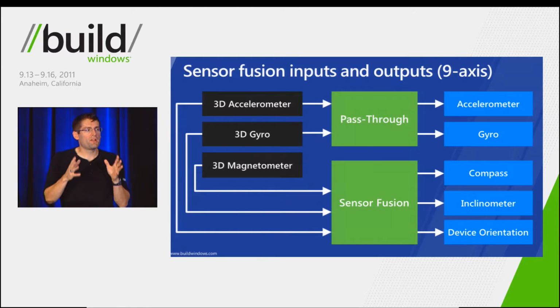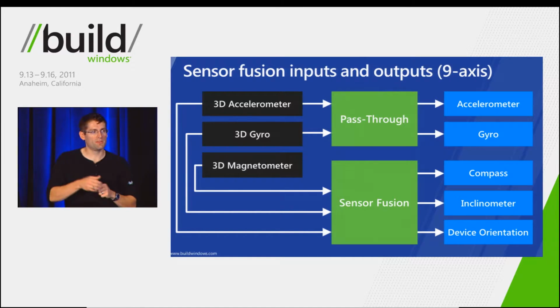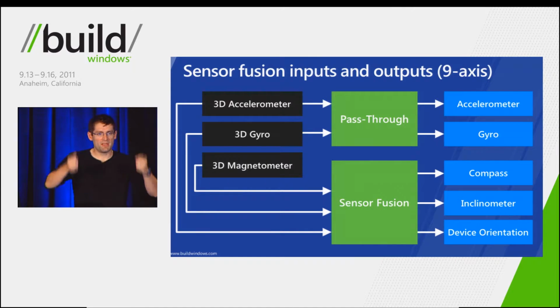But we can't really expose a seamless experience with just these two sensors because the magnetometer is a low data rate sensor and we have noise from these sensors. So we can add the gyro in, and that gives us a really fluid, responsive algorithm so that if we have electromagnetic interference, we can fill in the gaps. We can basically, for a short period of time, take the magnetometer out of the equation and do essentially dead reckoning for the heading part of that. When the device is being held up and down and is transitioning quickly, the gyro gives us that seamless responsiveness.